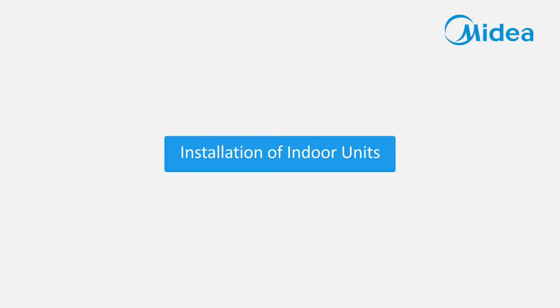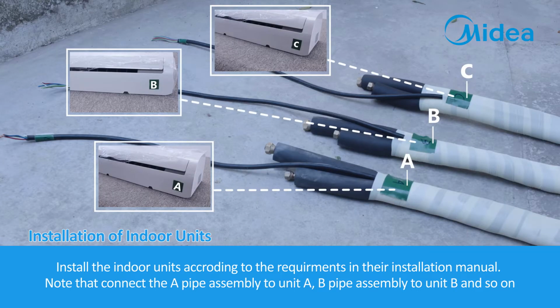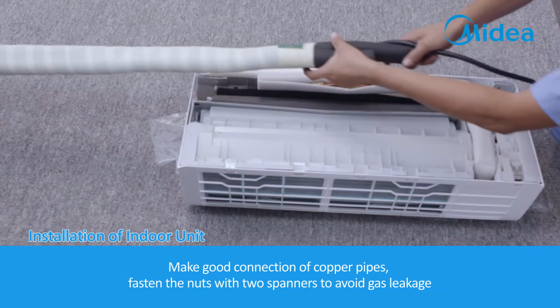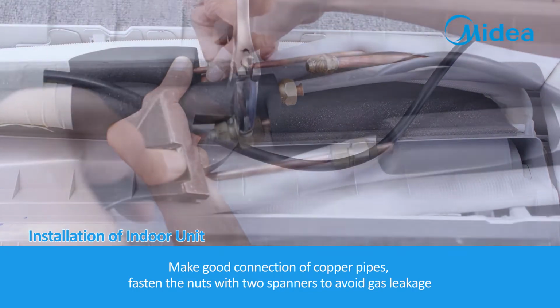Installation of indoor units. Install the indoor units according to the requirements in their installation manual. Note that connect the A pipe assembly to Unit A, B pipe assembly to Unit B, and so on. Take high wall unit as an example. Make good connection of copper pipes. Fasten the nuts with 2 spanners to avoid gas leakage.